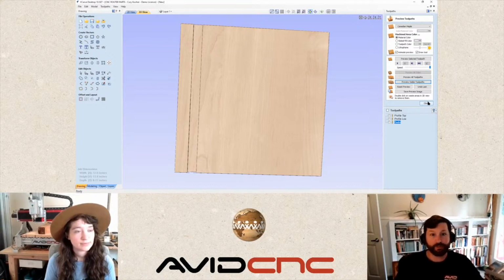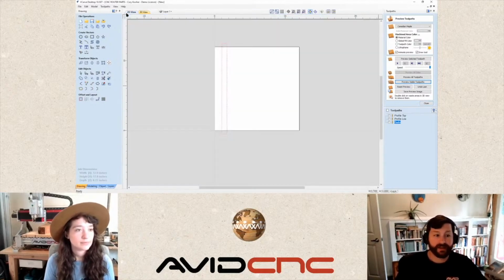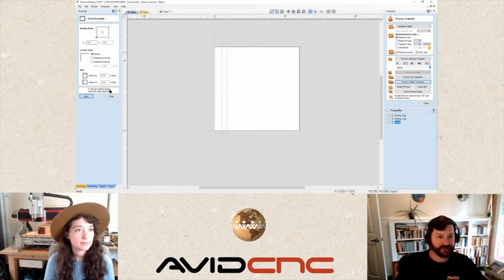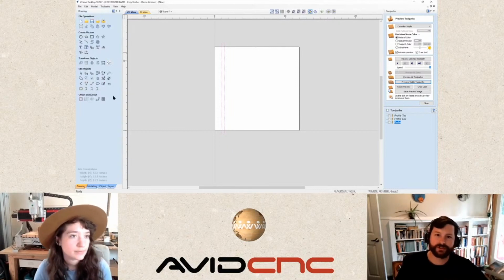What if we had a rabbet on another piece of material that we were wanting to accept here? And so a slot that was a bit narrower. So let's go ahead and change this slot dimension. Instead of 0.73, let's do 0.375. So we're going to be creating a narrower slot. And Sami, what kind of toolpath would you lean in to plywood on this?